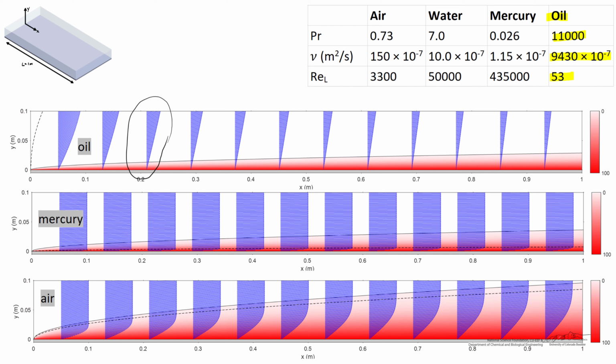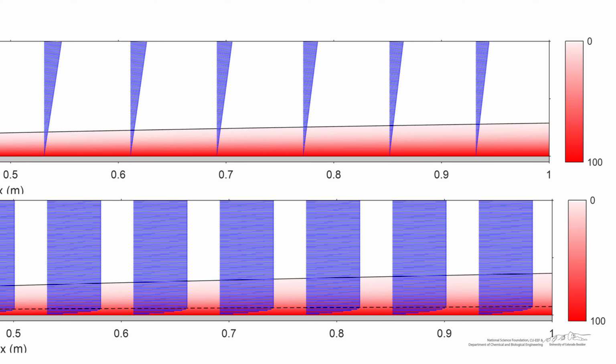And we see that within the velocity profiles as well. There's no region, unless we zoomed out on these charts, where we would ever see the velocity being equal to the free stream velocity. Oil just has that much viscosity. Let's zoom in and compare the effects.